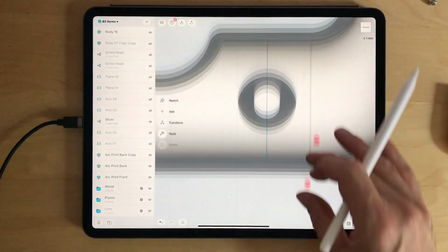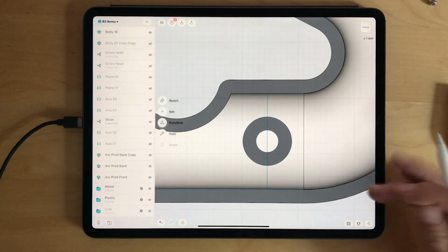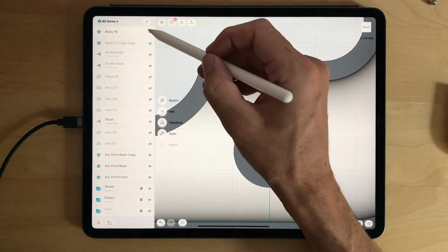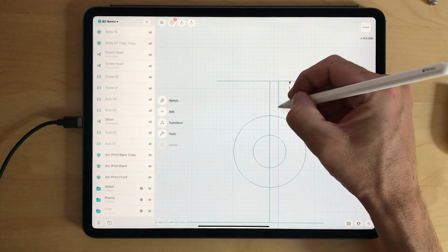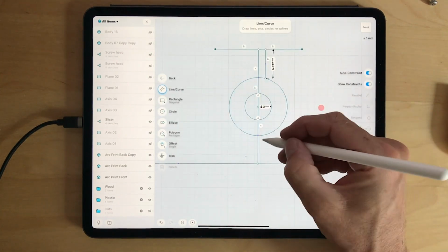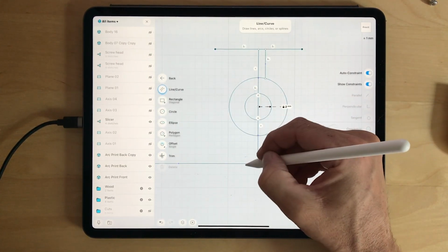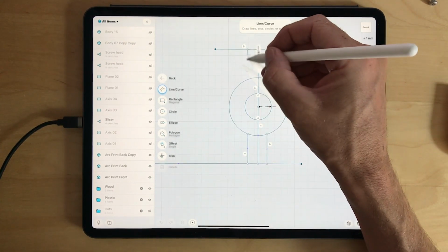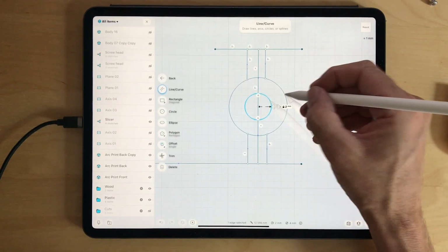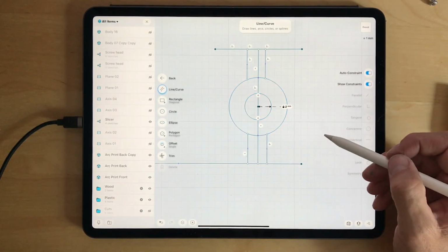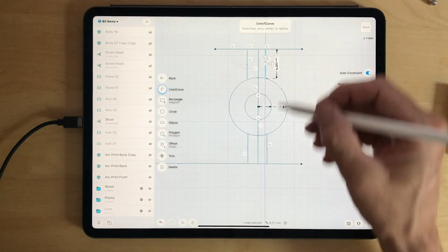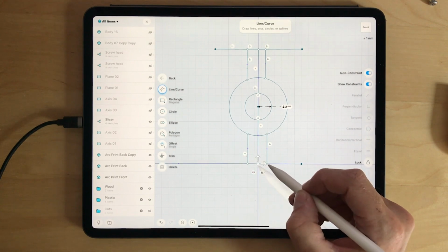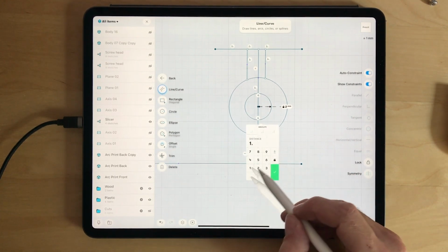Now for stability reasons, because 3D printing can be a little bit flimsy, this one I made the walls extra thick, so they won't break off. I can, however, in addition, add a little bit extra material. There. So these rings I want to lock so they don't move. Perpendicular, that's very good. So this should be 1.2 millimeters.